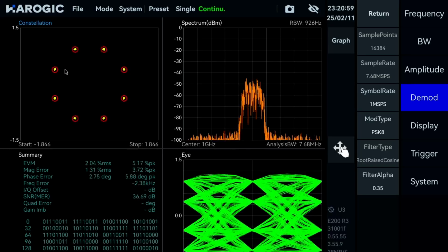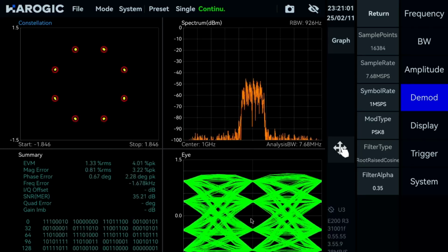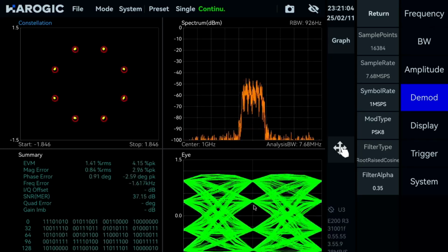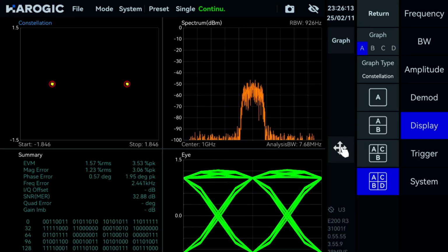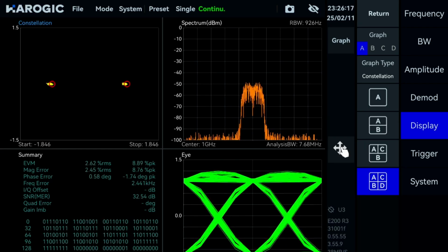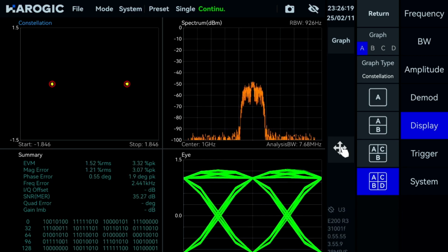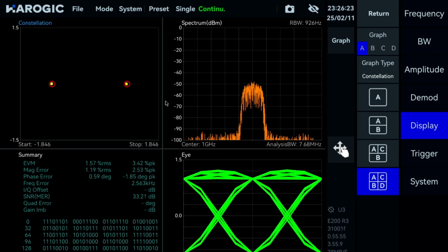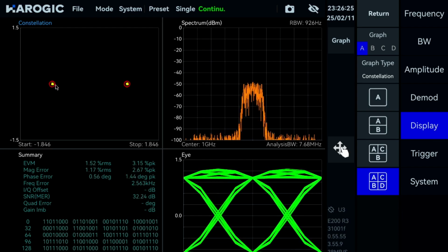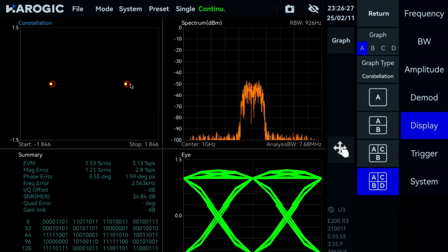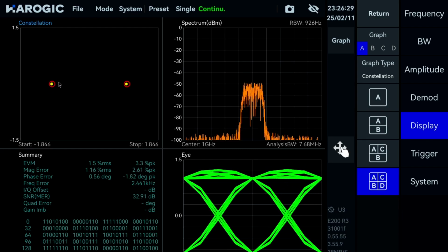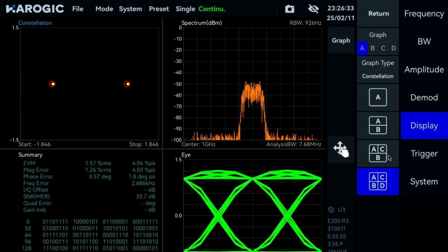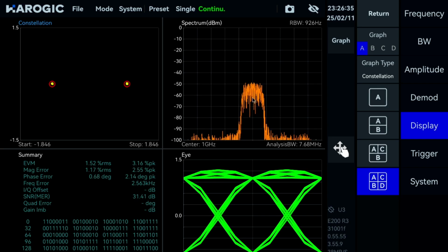But first, let's see, you have the eye diagram in here also showing. So for the first test, I actually chose the BPSK signal. I could actually also use a 2FSK signal in here, but we'll probably see it also later. But here in the constellation map, you can see the two symbols showing, the 0 here and the 1 on the right. So at -1, you have a 0, and at +1, you have a 1. You have also an FFT showing here.